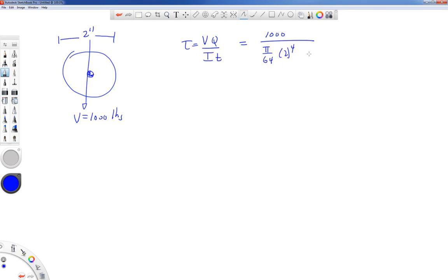And now the next thing I need to do is figure out where I can calculate my shearing stresses at. You can calculate your shearing stress at any level in this circle. However, you're going to have to use an integral unless it's at the centroid line. In my class in AEM 250, I'm not going to give you a place on a circle that's different than the centroid of the cross section or the top of the cross section. At the top, we know the shearing stress is 0. Let's calculate what it is here when our point of interest is a line that goes through the centroid.